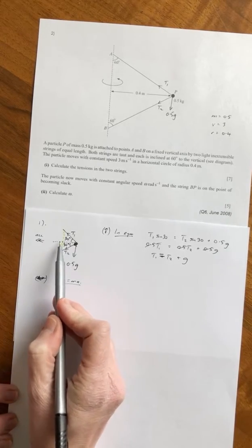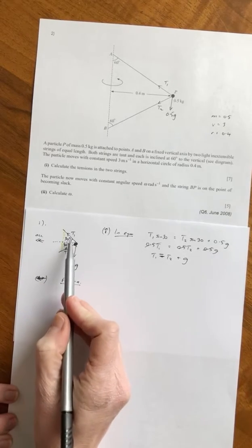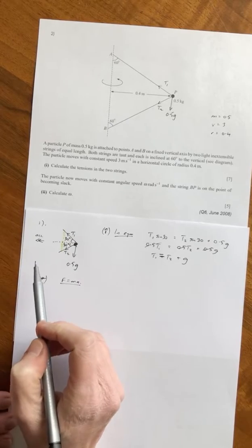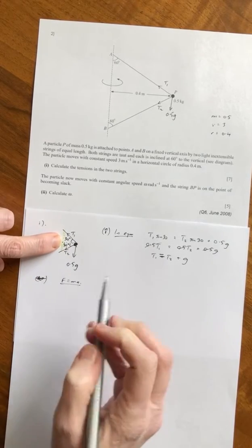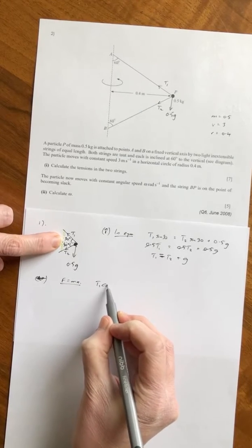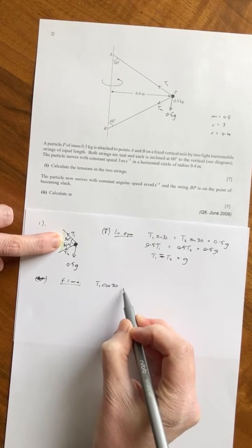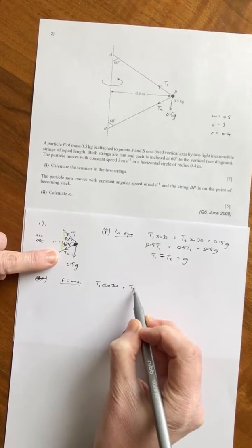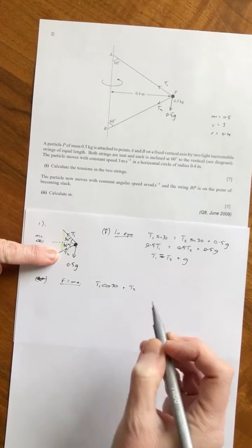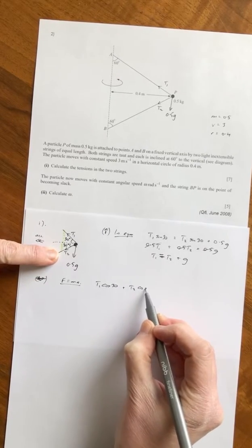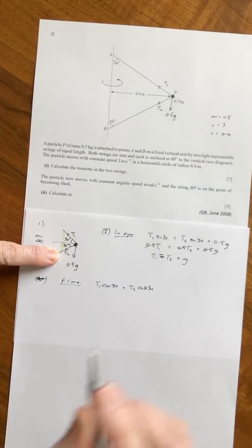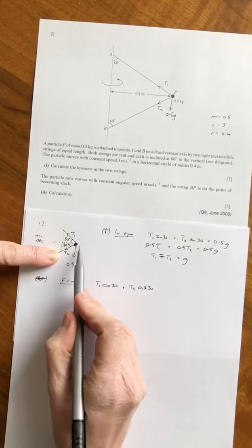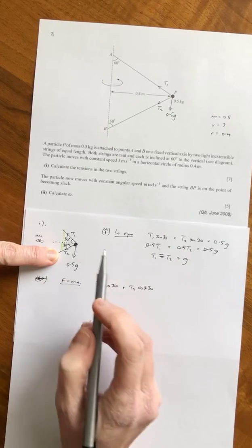So going in this direction, I've got both horizontal components of my tensions. It's going to be the opposite component to what we had up here. So T1 cos, because it's adjacent. The tension component from T2, of course, is acting in the same direction. So that's why I have got both of them being plus. There is nothing opposing the motion, nothing going in this direction.